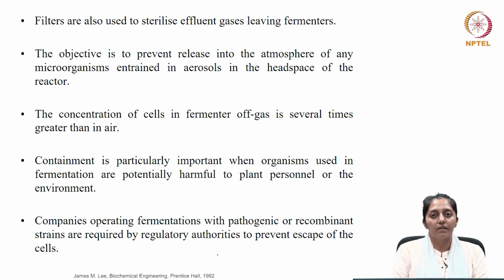Apart from the sterile air which is being sparged in, there is a continuous outlet of air from the headspace to release pressure. So, that effluent gas is also sterilized, passing through these filters before it moves out of the fermenter. The objective is to prevent release into the atmosphere of any microorganisms which get entrained in the aerosols through the headspace of the reactor.